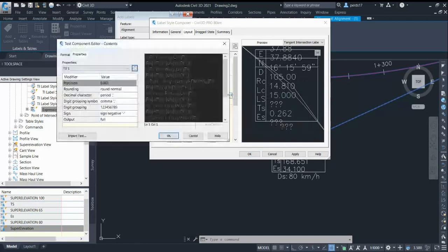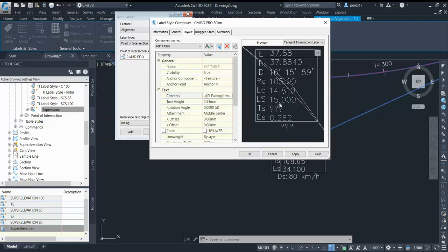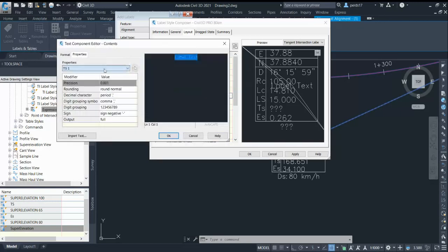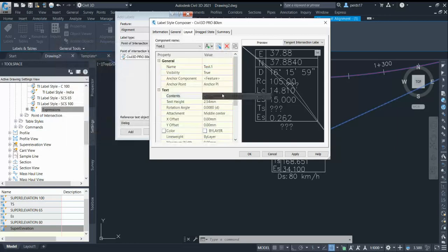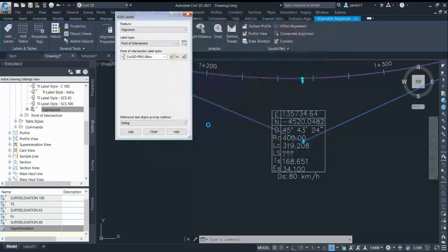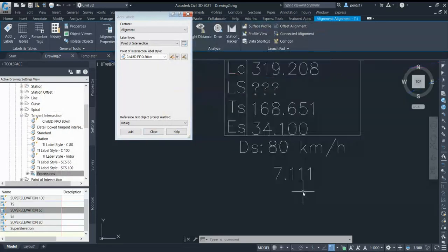So what I'll do, let's just remove it from here, click OK, because I already adjusted the table. Instead I add new text and add the value from here, click OK, and anchor it to my line 2 middle, and the y offset will be 8 and click OK. So you can see already my value is given as 7.1%.